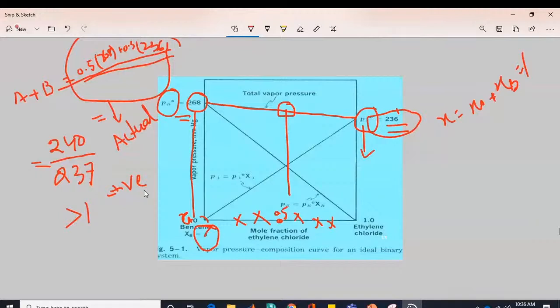Okay, let me take my pointer again so that I can be using this for your help. This is called the evaporation distillation or short path distillation principle. The substance to be distilled has very low vapor pressure. Examples are viscous liquids, oils, greases, waxy materials, high molecular weight substances. These boil at very high temperature. In order to decrease the boiling point of the liquid, high vacuum must be applied. So this is another thing that you need to apply high vacuum to those.